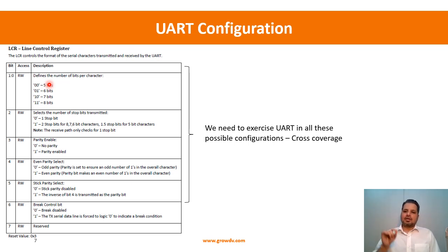So in this case, when it has been transmitted, you can sample LCR. When it has been received, you can sample LCR. Every configuration in transmission has to be exercised, and every configuration during reception has to be exercised. So you have to have this 6-bit counter, and you should have exercised both TX and RX with every unique value of those 6 bits. Only then have you completely exercised this LCR register.